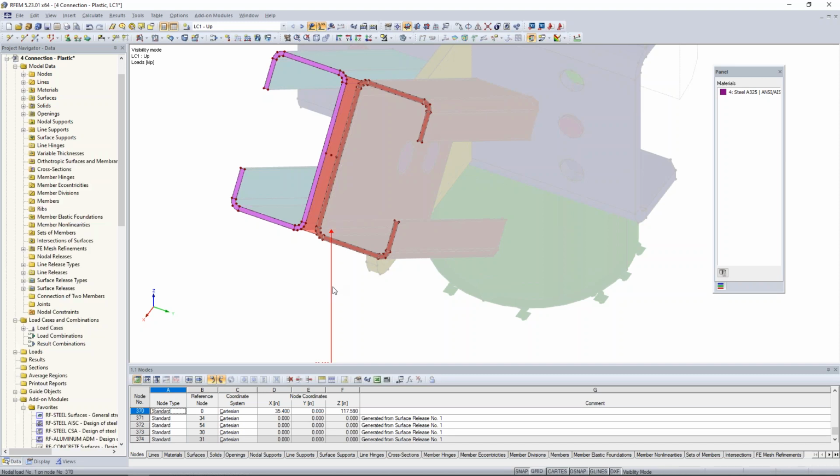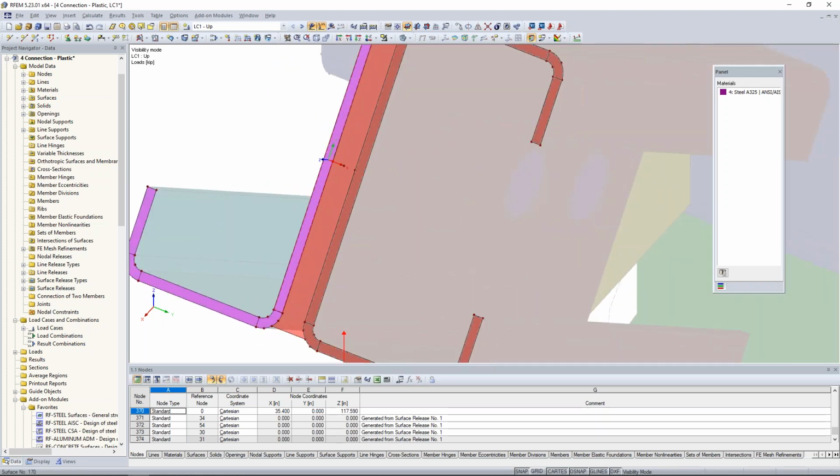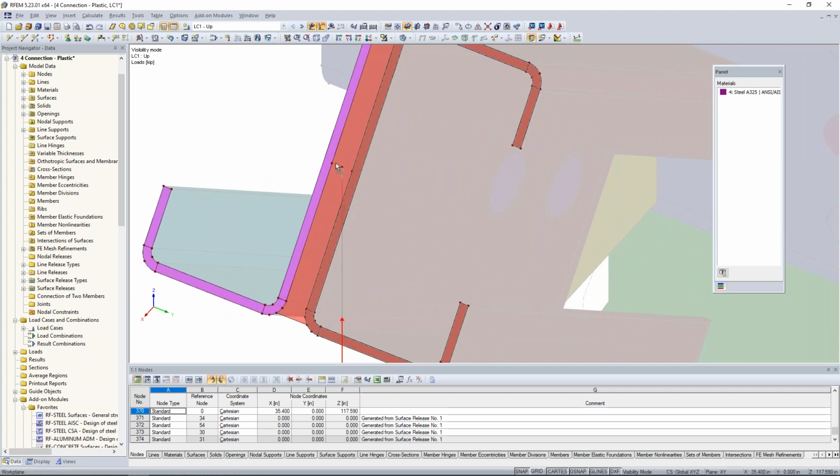The final thing to do is to modify where we're applying this load. Currently it's applied to this node that's really no longer active on that surface. So let's take this load and simply drag and drop it. Actually, let me zoom in a little bit closer. We'll take this load and drag and drop it onto this node on the left. So now that will be evenly distributed to the face of this channel section shown on the left.